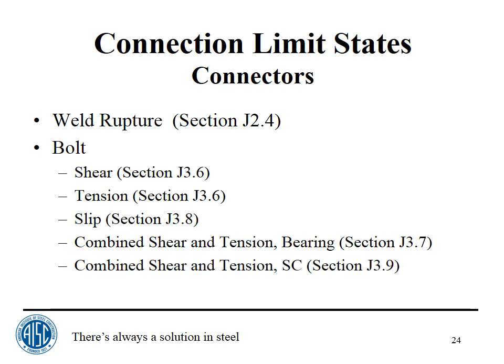I think people were thinking maybe it's a little bit redundant to do both, but I do think that logically it makes more sense to have a rupture limit state for the base metal adjacent to a rupture limit state on the weld. And I think that's the way it's going. If you look at the Seismic Manual now, there are some examples that are done with both yield and rupture, and some examples that are done just with rupture. This was in the 13th, and it's not in the 14th.